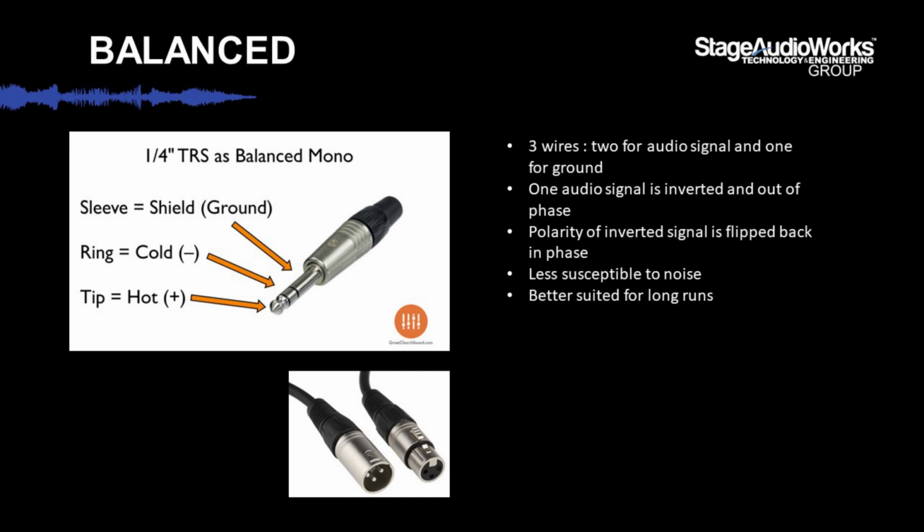A lot of times you've tried to plug a mini jack out of your computer, which is just a mini version of this thing. It also has a tip, a ring, and a sleeve, and then into a line level, which is balanced, and you push the fader up and you hear this really weird, crazy sound where the vocals sound like they're cancelled out and there's no low end or anything like that. And if you pull the jack halfway out, you kind of hear the full signal again.